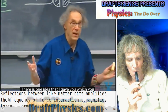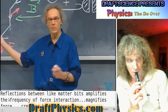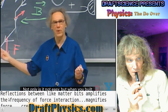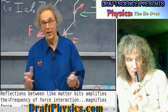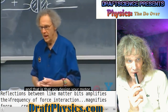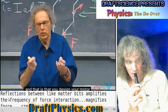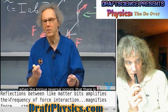There's one idea that I gave you which you may ignore, and that is to overcome the torque reversal, you can build a commutator. That's really not easy. Not only is it not easy, but when you build a commutator, your system may get a lot of friction, and you may lose more than you gain. There is an alternative solution, which I mentioned in my handout that you picked up today: you design your motor in such a way that when the torque reversal occurs, there is no current running anymore.